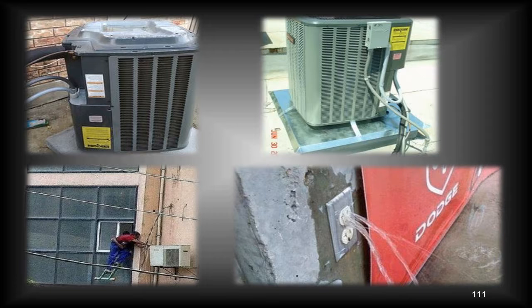You can see clearly this is on a rooftop. They have the disconnect hooked right to the condensing unit. It is on a panel that is a removable panel. That panel is able to come off in the event that we have to make a repair on the condenser coils or need to clean the condenser coils. So you could be subject to having to do something a little bit different there.